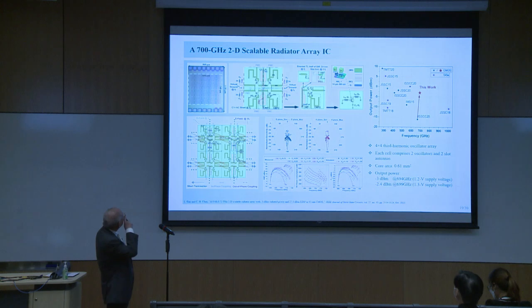So we continue to extend our terahertz source, and it is 700 gigahertz, which makes use of the third harmonic. Again, we design our IC such that it gets the highest output power for frequencies beyond 600 gigahertz. The power here is also 0.57 milliwatt, but at a much higher frequency. So it is very difficult to do.